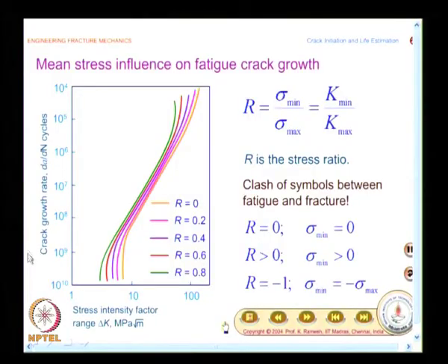Without exhaustive material testing, you cannot employ fracture mechanics, and R ratio is a factor, but from this graph it shows that the slope remains same, but C changes, that is what we find, but you will have to look at the data handbook how they report the results.